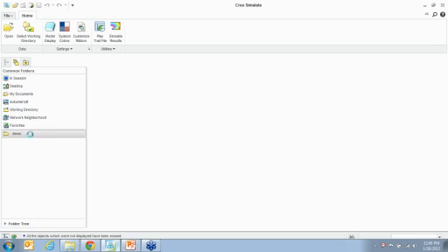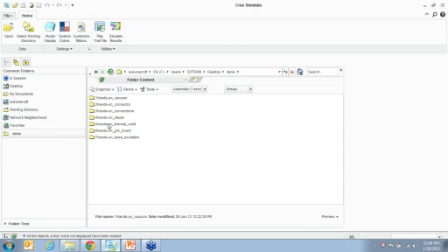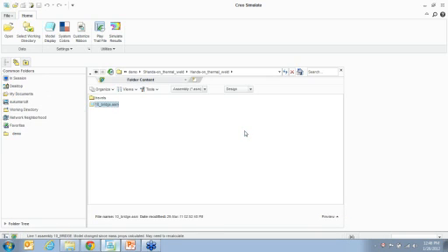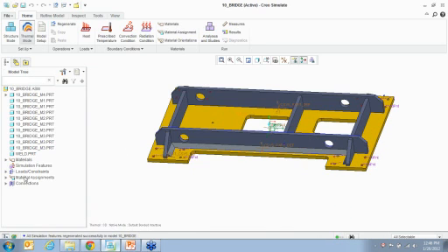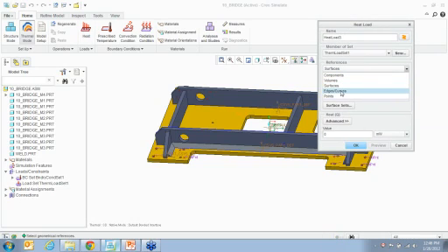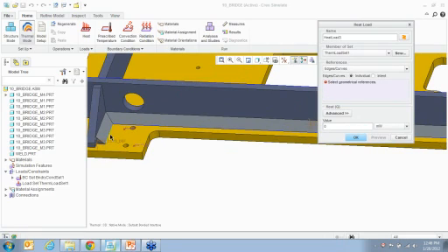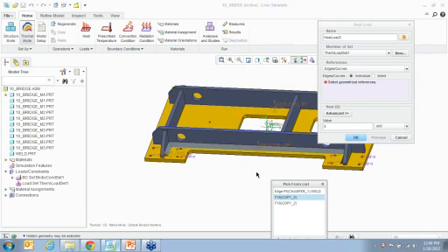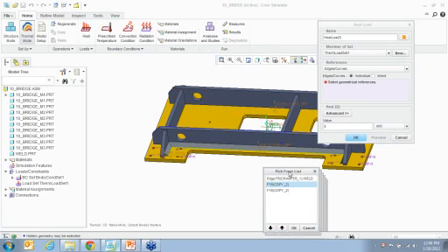We're almost done. We have this, and then we'll do a little Q&A, and we should be good to go. So let me go ahead and set my working directory. Working directories are very important. So right here we are in the thermal mode. So you have all these boundary conditions set. So let's apply a heat load. Heat load on a curve. Now I can right click and pick from the list. Notice it highlights the whole curve in green right there. We can go ahead and pick them.